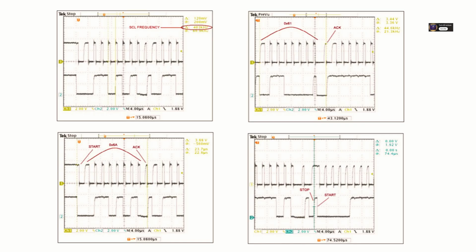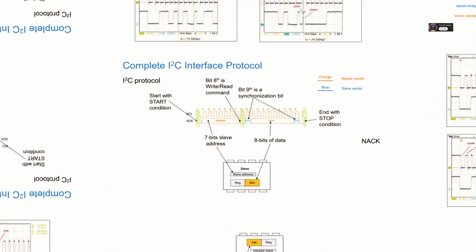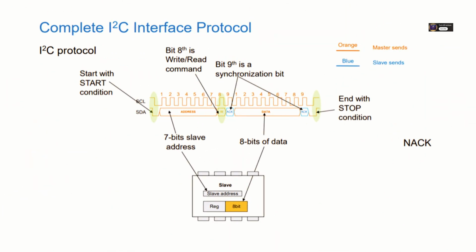So what are the usual suspects when data gets corrupted or communication is flaky? The top things engineers should check. Okay, common culprits. 1, electrical noise. Poor grounding, noisy power supplies, running I²C lines too close to high-speed switching signals. 2, incorrect pull-up resistors. Too weak gives slow rise times, too strong overloads drivers or wastes power. Get them right for your speed and capacitance.